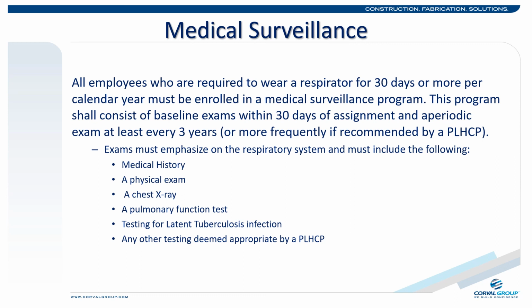If a respirator is worn for protection against respirable crystalline silica, the number of days that the employee wears the respirator must be tracked. Employees must be enrolled in a medical surveillance program prior to having worn the respirator for 30 days. If you or one of your employees will be required to wear a respirator for silica exposure and suspect that it will be worn for 30 days or more, please contact your safety manager.